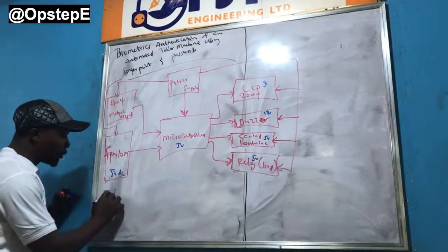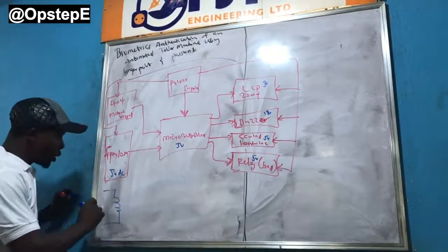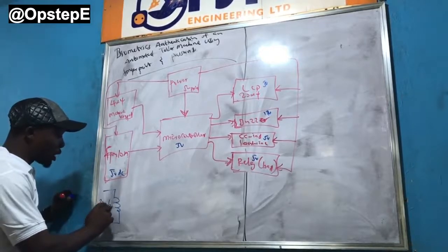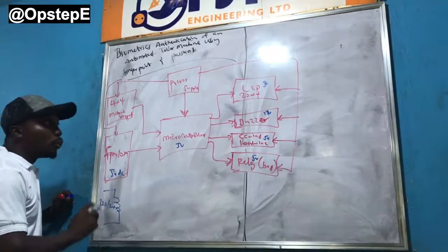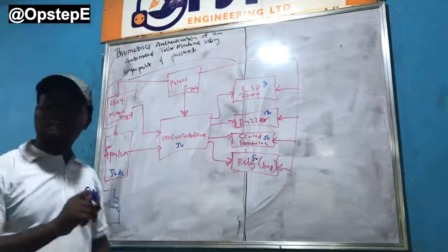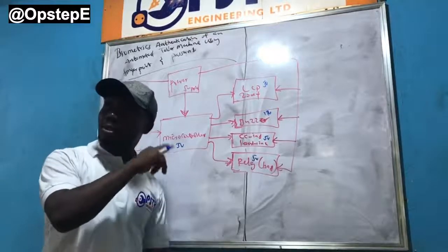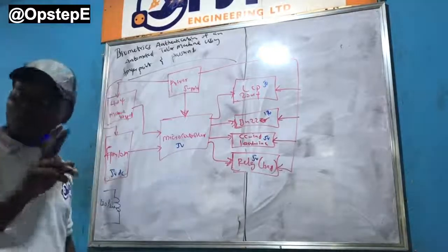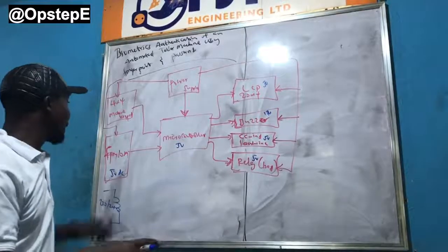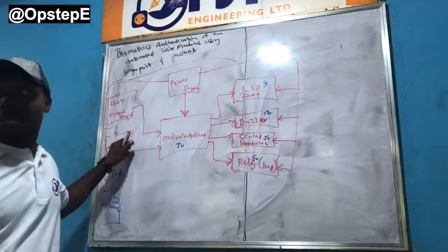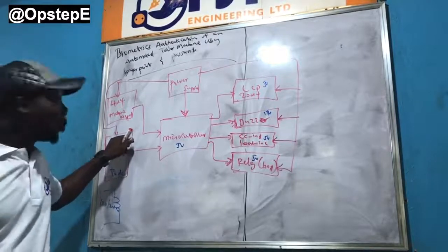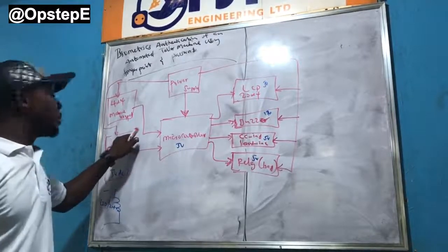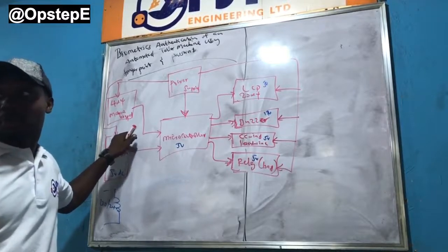We would have gotten a transformer. Don't forget, a 220/240 volt transformer. We also need to be sure that the transformer can supply the current the system requires. From the quick observation we did this morning, we know that this one sources more than 150 milliamp, like you said. My assumption is that it uses around 1.5 amps to come on or to operate.